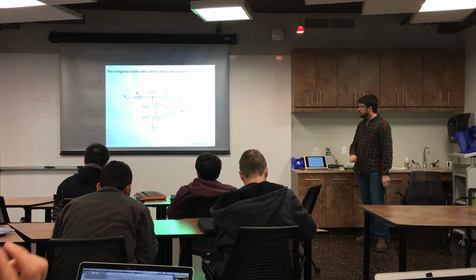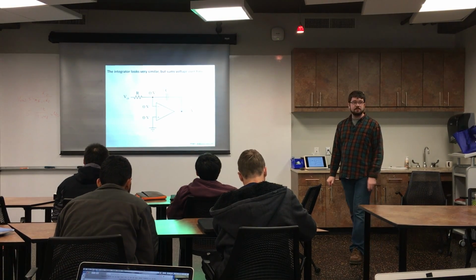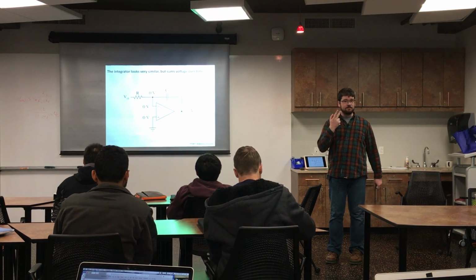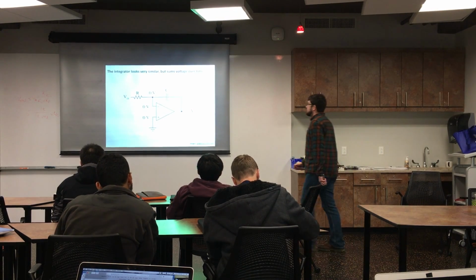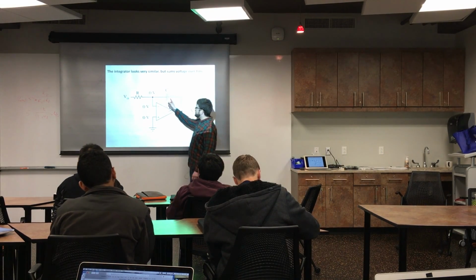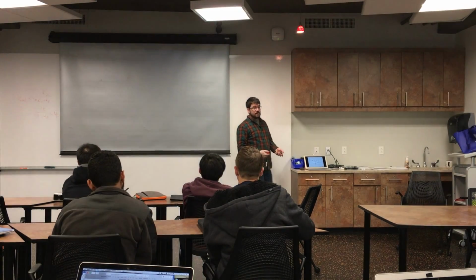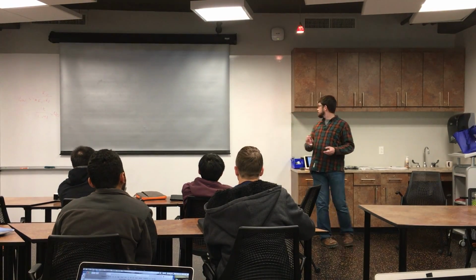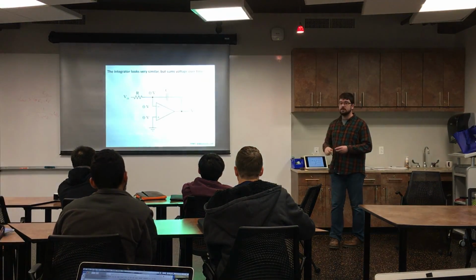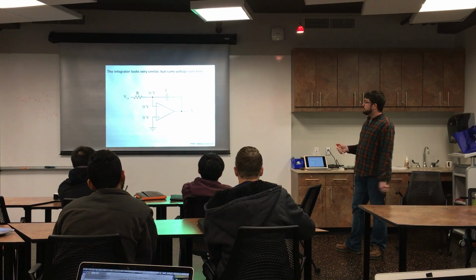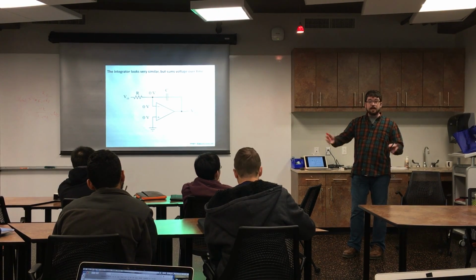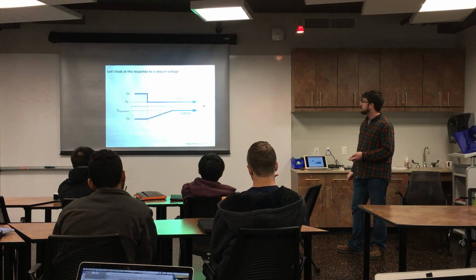And the integrator is basically the same thing, except the capacitor and the resistor have now swapped places, and we are now charging this capacitor through this resistor, and it's all in the feedback network. What we end up doing is sort of creating this time averaged sum.